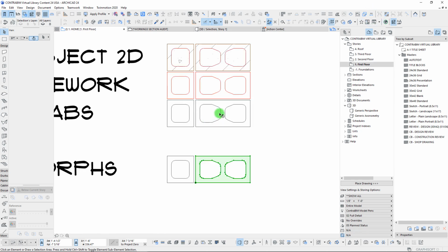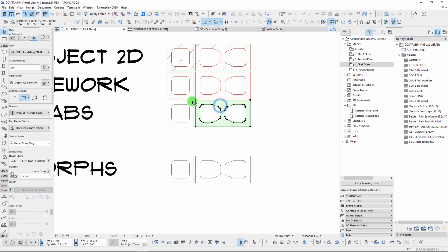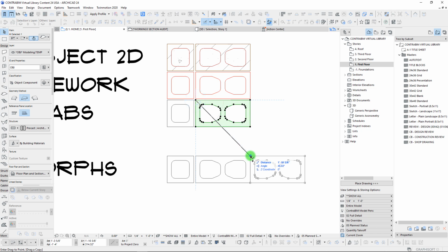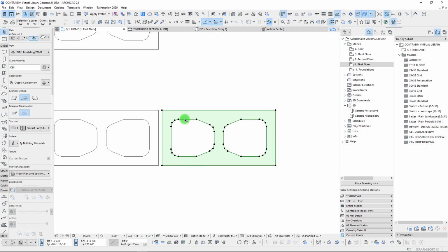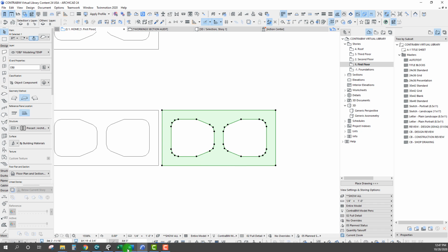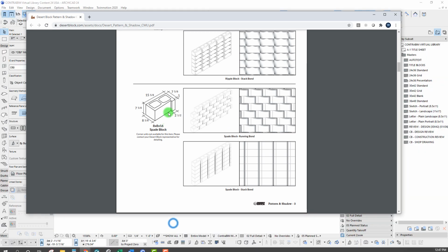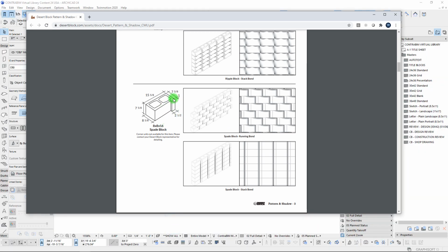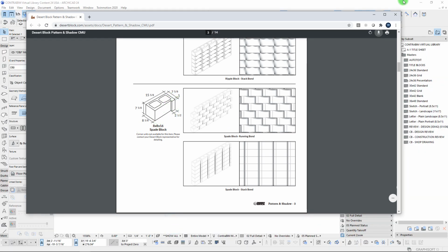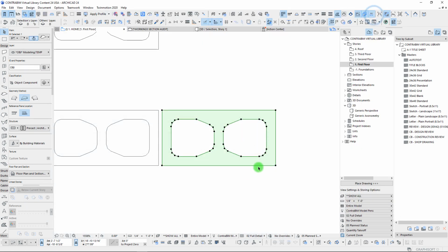So what I think I'll do is take this slab here and copy it over, and give it that little bit of a gap that we were using. To point out how we're going to set this up, we want it 2.5 inches. We're going to extend it 1 inch, and then we'll angle it. Okay, so from here, let's just measure over 2.5 inches.